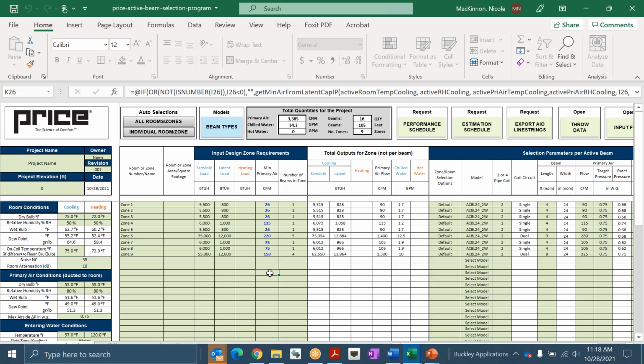We realize it's not always possible. Maybe you're doing a retrofit and you're locked into your equipment. You have to work around those parameters, but the ideal scenario is that you start with the chilled beam software, zone level selections, and you back that up to the equipment level and select your equipment around your space needs at that point. So great question. That's the process we would recommend.